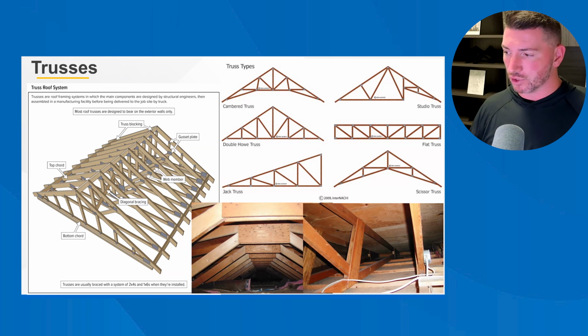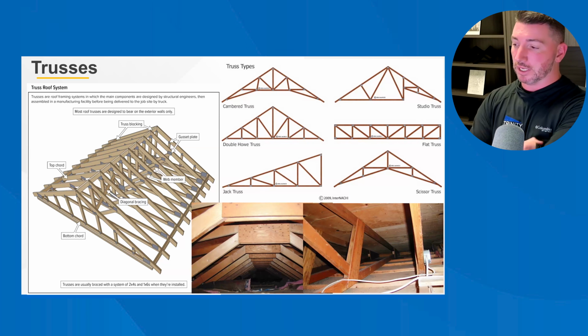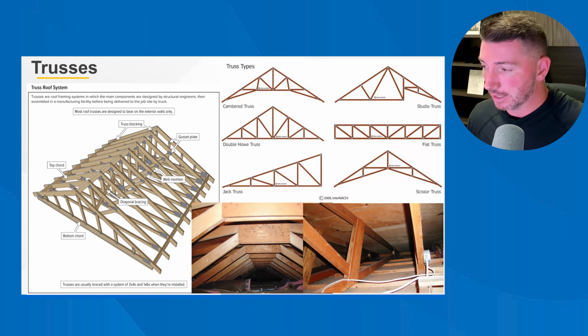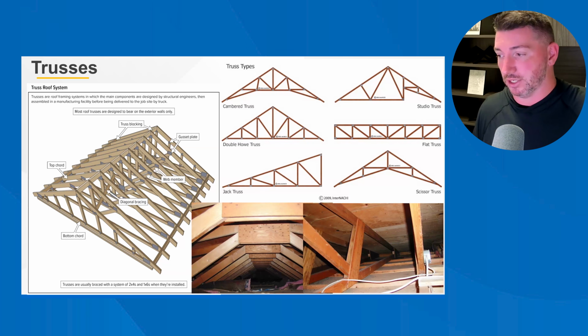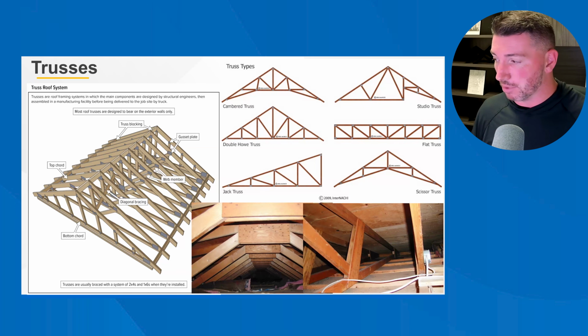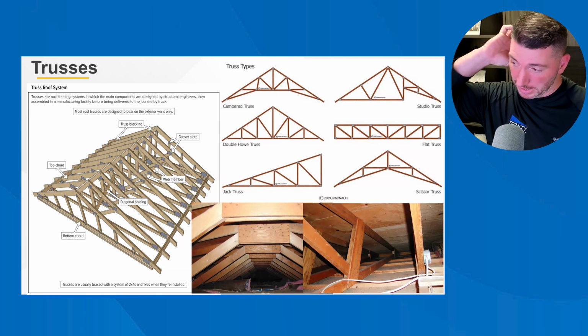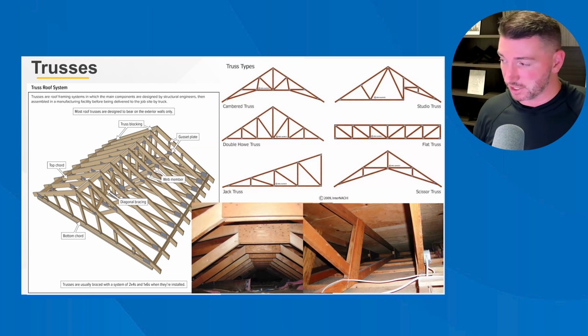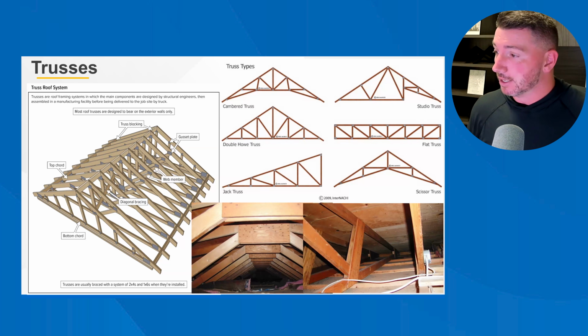Now, those ones in the middle bottom, that would have to be something that was signed off on by an engineer because those are wooden gusset plates and they're usually supposed to be metal, manufactured at a truss facility. Both the bottom middle and the bottom right just look like they're older systems that somebody added in lumber to create a truss system that I don't trust very much, frankly. That one's for free. So if you're not sure what you're looking at, look for the gusset plates.